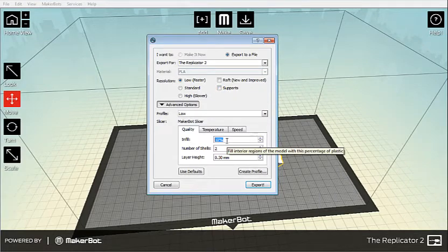The infill percentage is a great way to change the mass of the car, or if you're working on your bridge project, it can change the strength of the bridge very easily. So infill is the amount of plastic inside, and it'll actually lay it down as a hexagon structure. Normally by default it's 10%. I recommend anything from like 10 to 20%. It goes all the way up to 100% where you'd have a solid block of plastic.